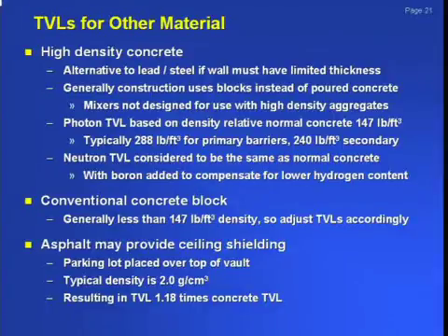And the other common material you run into is asphalt, because they'll typically put a driveway a lot of times on top of your linear accelerator. It really helps isocenter stay stable. But you will have to take into account the amount of asphalt. If you think about it, asphalt is actually really good for neutrons because it has a lot of carbon in it, a lot of hydrogen in it.